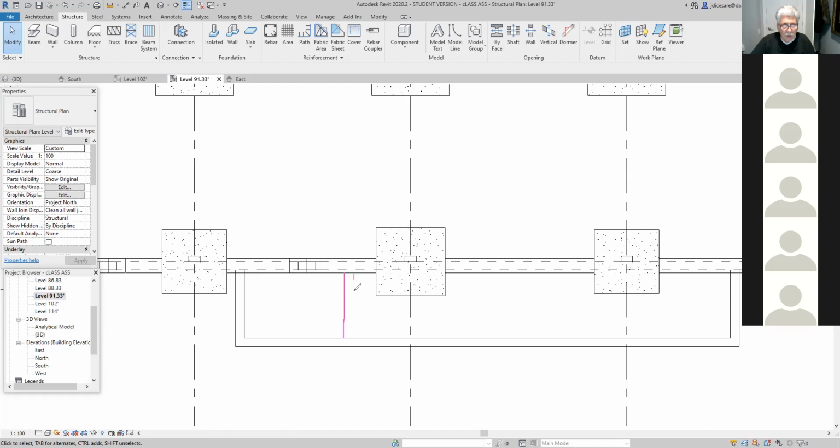I don't see it in plan view, but I see it in section EE. And from this wall to this wall here, according to the dimension I see on top on section EE, I have 13 feet 4 inches. So this wall has to be 13 feet 4 inches away from there, from the outside face to the outside face. So that's what I need, 13 feet 4 inches there.